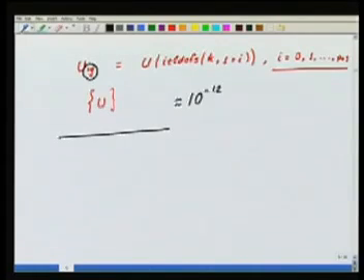Once this set of tests is done, then we know that at least the part of our element matrix coming out of the stiffness only, not the spring part, is correctly done. The load vector calculations are properly done, and the boundary conditions are properly applied. So, if I go up,